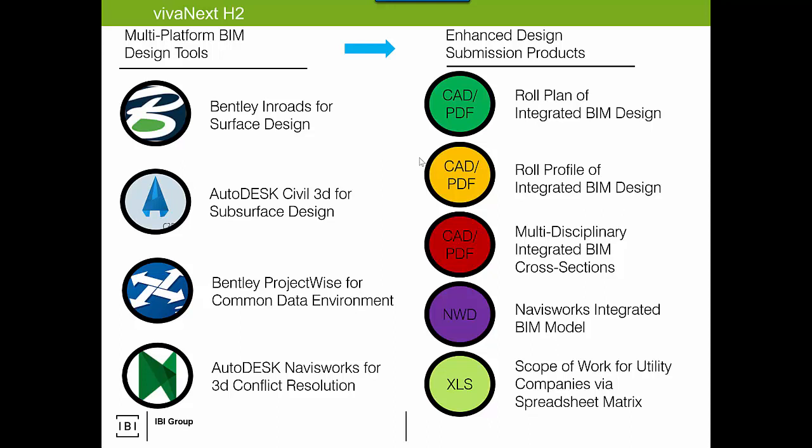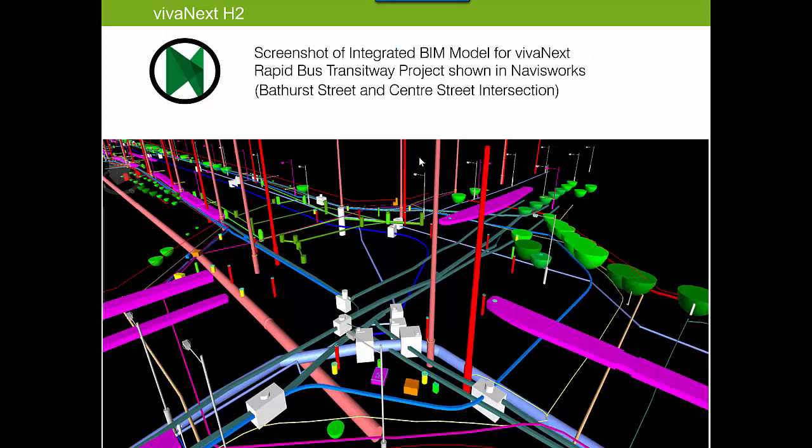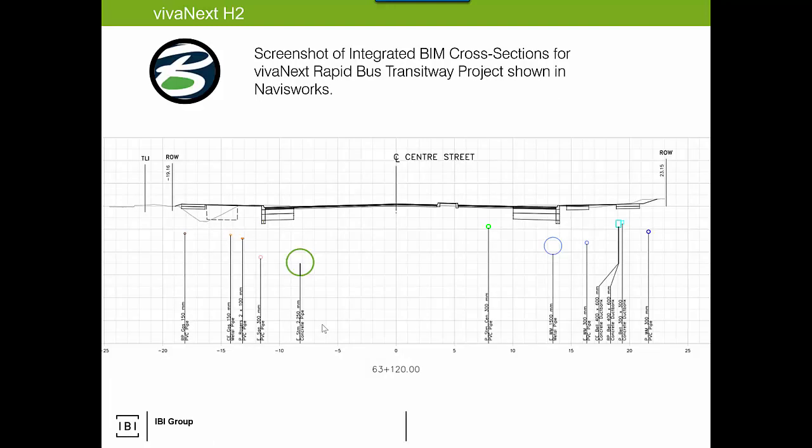We had modeled electrical posts, electrical lighting with foundations, telephone poles with foundations, sewers and catch basins, existing and new utilities, root bulbs, landscaping, etc. Everything was here. Everything was analyzed. Clashes were detected, like you can see right here, and then mitigated and resolved accordingly. Drawings were developed straight out of the models, identifying where the components were, their elevations, full 3D, full analysis, relation back to the surface. Live ProjectWise for the authoring of the AutoCAD-based files for Civil 3D.